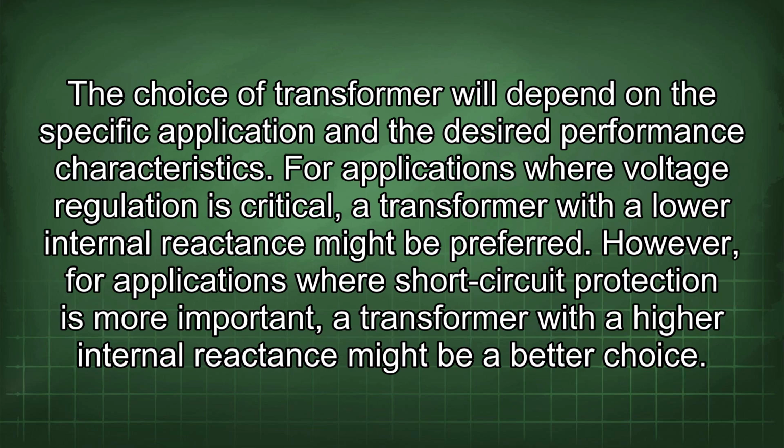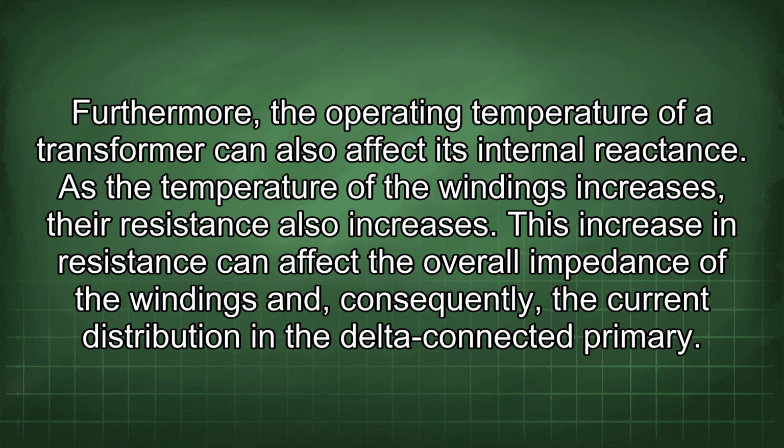For applications where voltage regulation is critical, a transformer with a lower internal reactance might be preferred. However, for applications where short-circuit protection is more important, a transformer with a higher internal reactance might be a better choice. Furthermore, the operating temperature of a transformer can also affect its internal reactance.